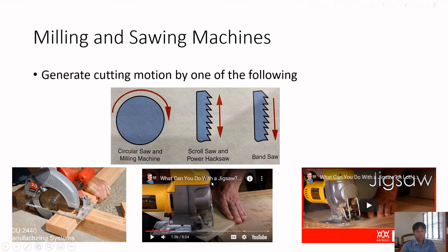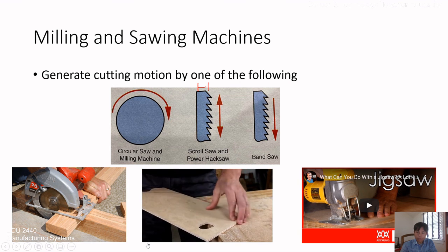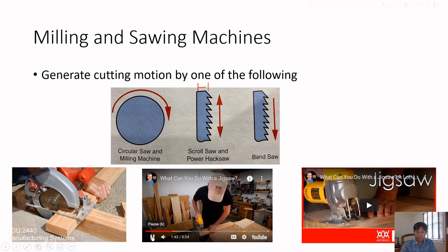But this jigsaw has a very small width, so we can change the direction. That's the advantage of the jigsaw. It's handy for cutting holes, something a bandsaw can't do. Its biggest limitation is that you can't cut really thick lumber. Usually this isn't much of an issue.